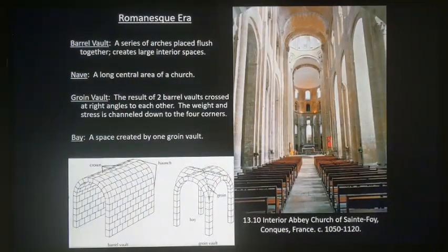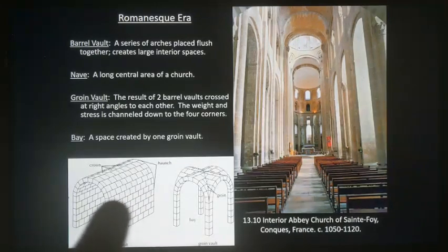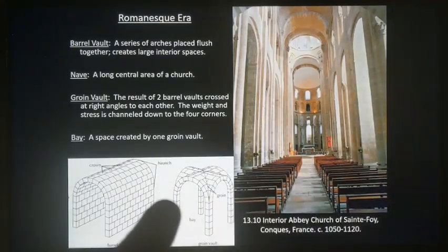The greatest architectural accomplishment for the arch is arguably the cathedral, which we have many examples still standing in Europe that we can still see this barrel vault. So when you take one arch and extend that through space, you're creating a barrel vault. Underneath you have a gathering area, the nave, which is this structure inside the cathedral. And if we take two of these barrel vaults and intersect them perpendicularly, we have a groin vault.